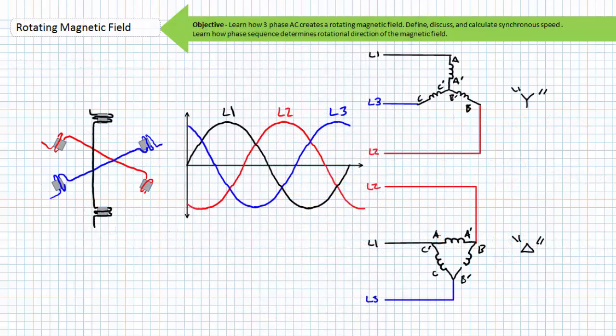Now let's move beyond our earlier simplification and see how 3 phases interact with each other. Again, this is not meant to be a lecture on motor windings. Even these details are at best cartoonish simplifications. Let's start by examining a 3-phase AC single pole pair per phase stator. One could also say that this is a 2-pole per phase stator, or since it's designed to run on 3-phase AC, a 6-pole stator. The stator necessitates 3 windings, A, B, and C, one for each phase.